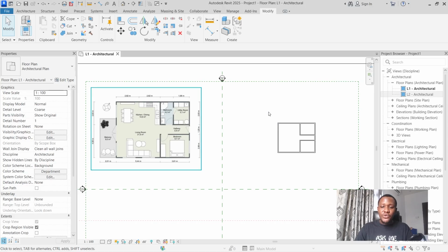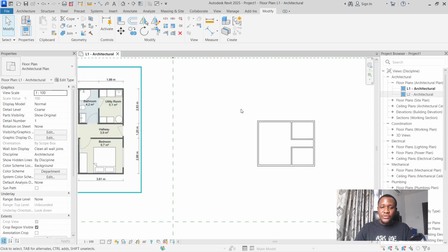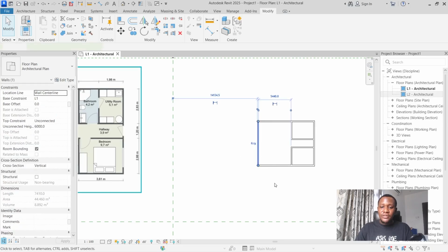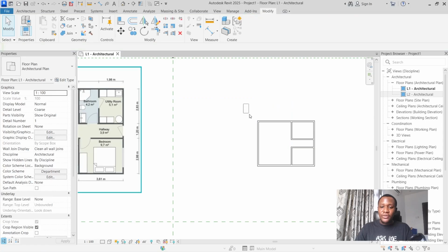So in Revit, there are two ways you can actually select an item. So I can click the mouse and drag it towards the right hand side. That's going to create a square that is straight, not dotted. I'll explain much later. So once you click this square over any element, it doesn't select anything. That's because you have to select the entire element for it to become selected. So once I click this and drag all the way like this, once everything is selected in a whole, it becomes selected. But if you touch anything that is not fully selected, it will not be selected. So we need to select everything.